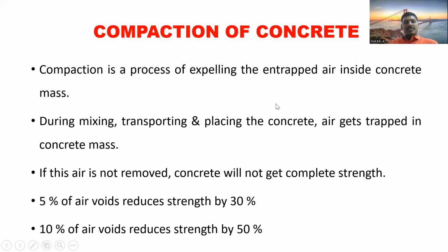Okay. So the next point is the compaction of concrete. After the placing, compaction is also a very important factor, because if we do not compact concrete properly, voids and segregation voids will be present, the porosity will increase, and the concrete may show honeycombing. We have to avoid that, so we have to compact the concrete. So how to compact the concrete?